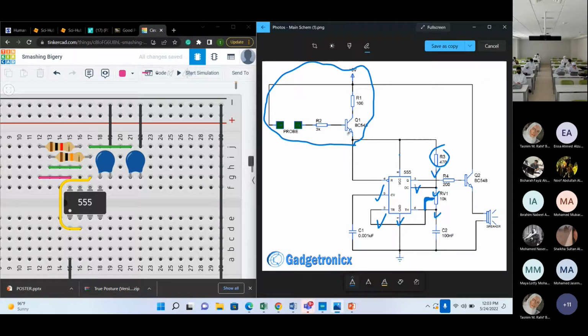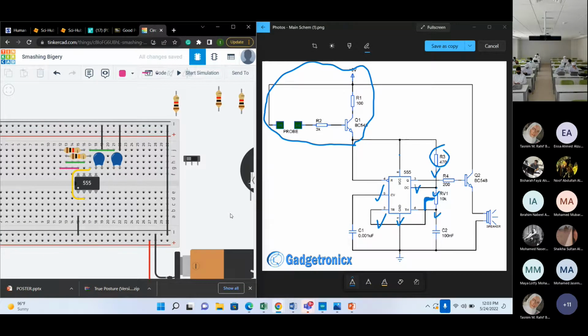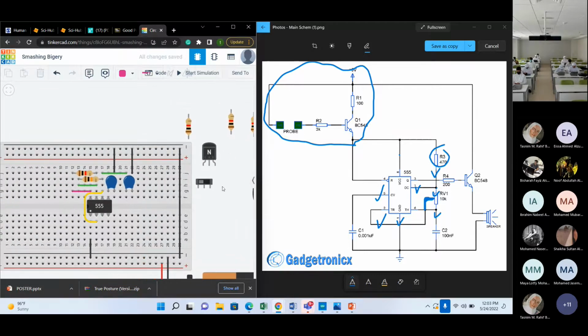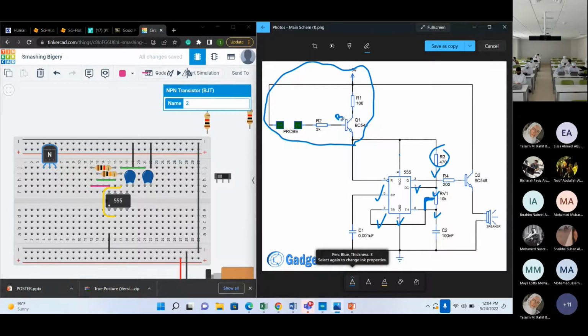Well, first of all, we need to add the transistor. So what am I going to do? I'm just going to zoom out a little bit, get the components that I need. In this case, I'm going to need one of the transistors. I will also need 2 resistors and these switches, right? So I'm going to take the transistor now and place it somewhere where I have an empty voltage line. All of these voltage lines are empty and I can use them, right? If you remember, we had a base on the transistor, a collector, and an emitter, correct?